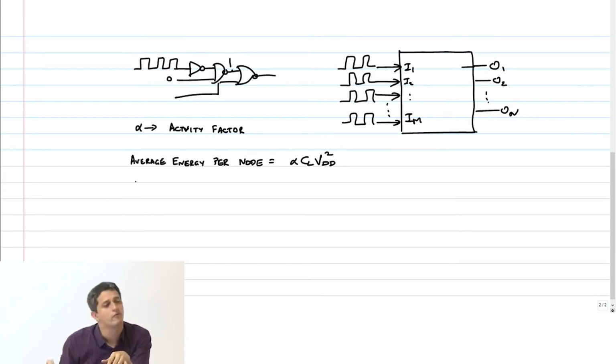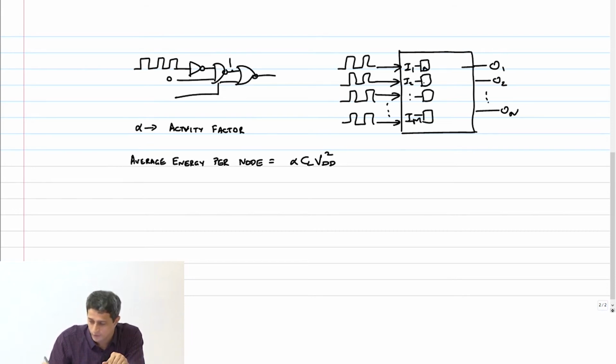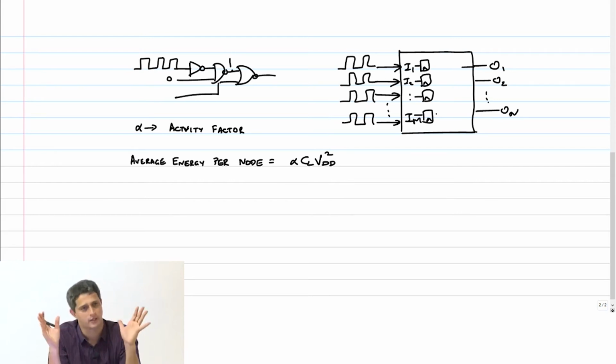So now how do we convert this to power? Typically these inputs here, if you look at this circuit, will get buffered through flip-flops. So the input can change only at every rising edge of the clock. Even if you apply it at a faster rate, it will not reflect in the change inside the circuit. So you can assume that all the inputs are synchronous and there is a central clock which is controlling the entire circuit, right?